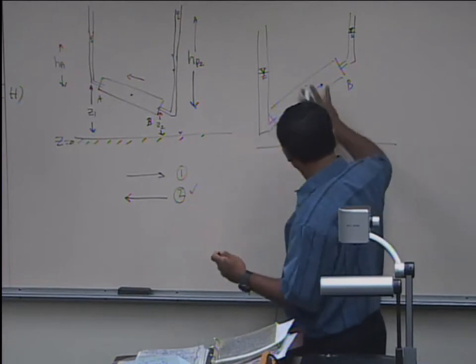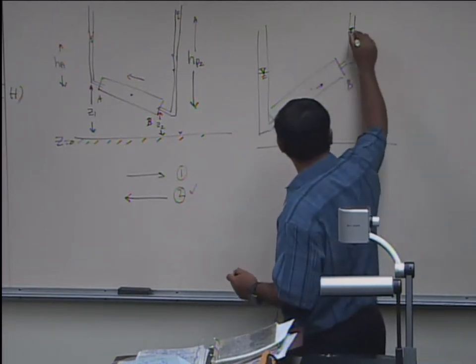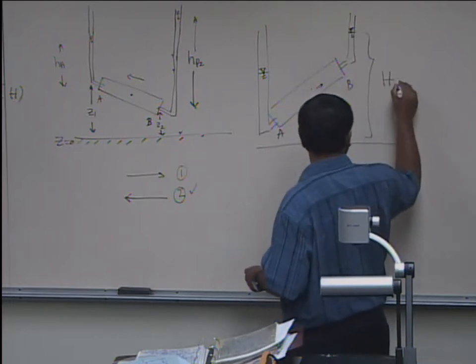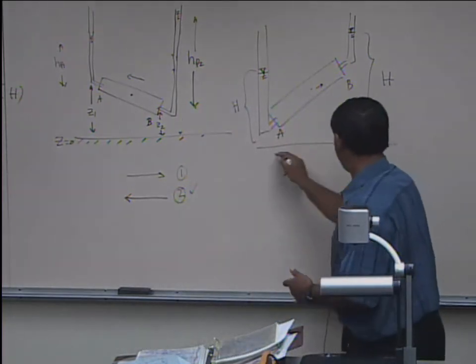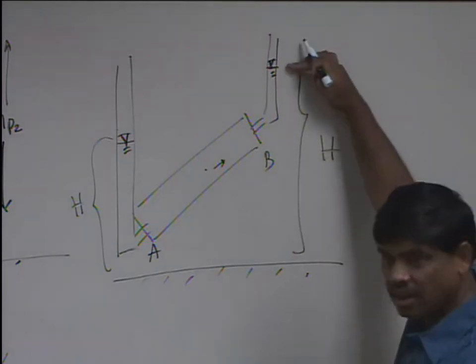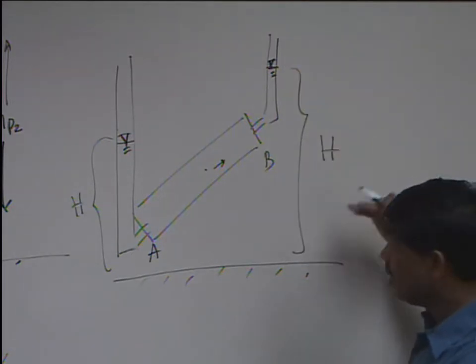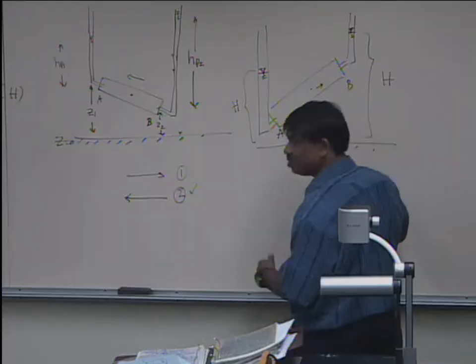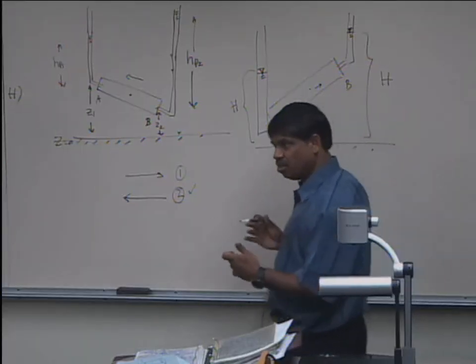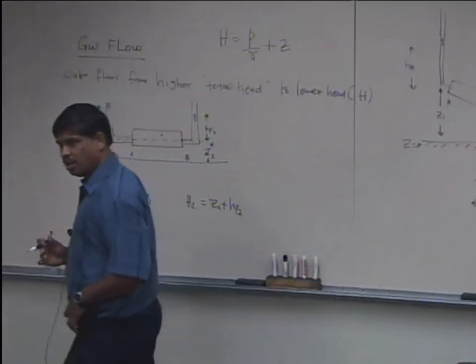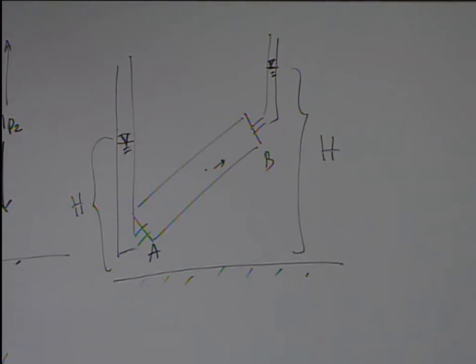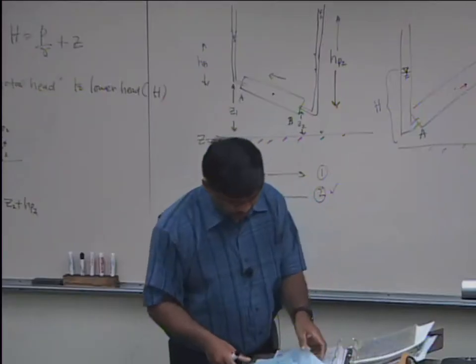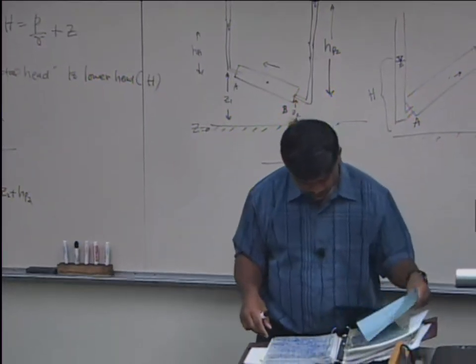Again, it's the same idea. Forget about the orientation of the column. It's always the total head. So basically, you measure the total head. How is the head measured? Well, you create a datum. Head is nothing but the water level above the datum. And the datum doesn't matter. I can create a datum here. It'll still work out fine because it's a uniform benchmark. So groundwater flow is always dictated by the head level, the water level, measured from a fixed benchmark or datum.